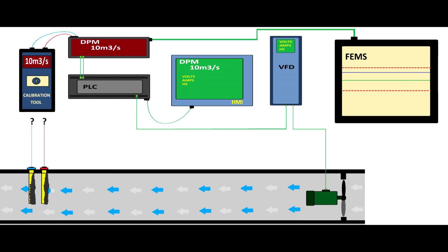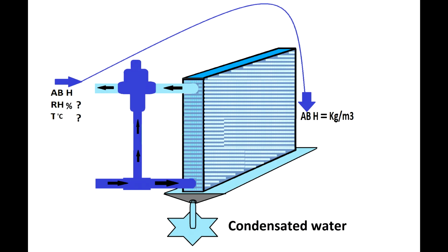This is the main reason why I disagree with this type of calibration, where we calibrate the DPM ignoring the pitot tubes which send data to this differential pressure module. This is an incorrect calibration. An incorrect calibration will lead to wrong pressure or air change rate reading.